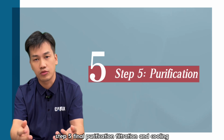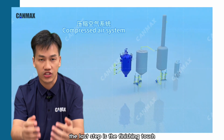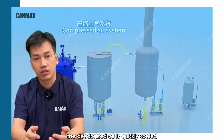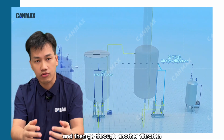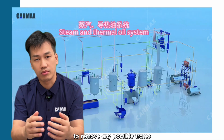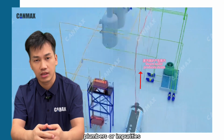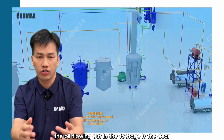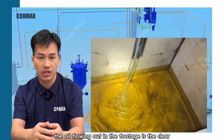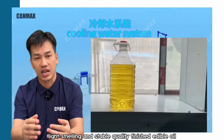Step 5. Final purification, filtration, and cooling. The last step is the finishing touch. The deodorized oil is quickly cooled to below 60 Celsius and then goes through another filtration to remove any possible trace impurities. Now the entire physical refining process is complete. The oil flowing out in the footage is the clear, light-smelling, and stable quality finished edible oil.